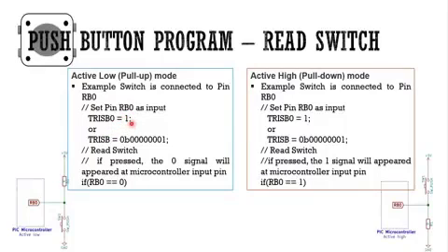And then this one is decimal, or you can also write in binary format. We want to use only bit 0, so we put 1 here. You can also put 1 throughout the rest of the bits, provided that you are not using the rest of these bits. If you are using them, you need to try to avoid this, because it will become a conflict with the rest of the load. So better, if you want to use RB0, set bit 0 only.